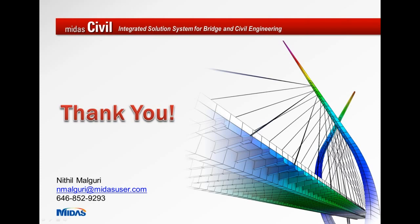There is another question by Mohammed. The question is, should we consider two opposite direction springs at each pile section to consider passive and active situations? Well, in the case of a pile, there is no passive or active situation, because if it goes towards one end, it's passive for one side and active for another side. So we just model one spring that contains the stiffness for active in both regions, because active is higher than the passive one.